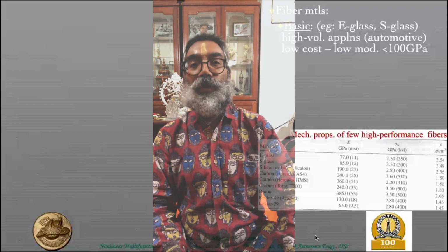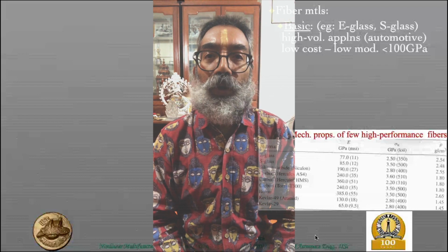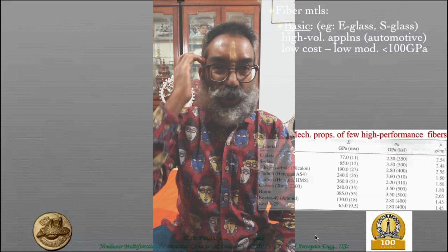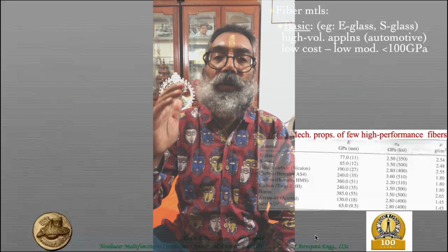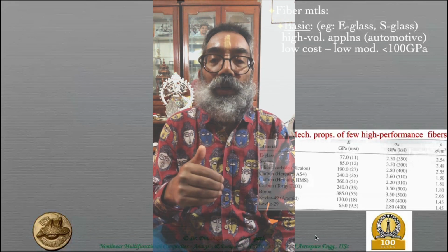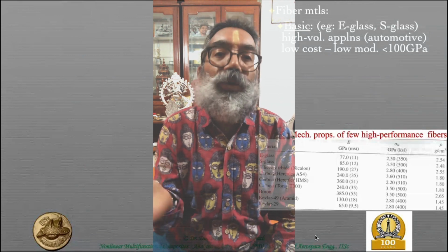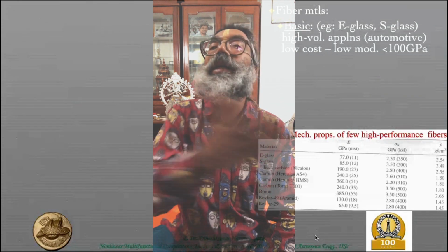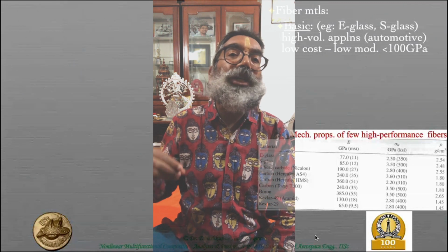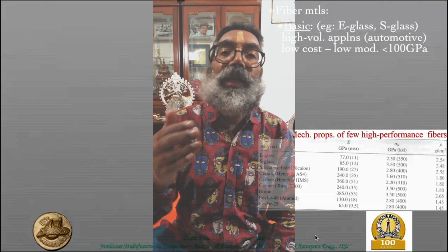That's correct. Very good point you brought about. We will look at all those failure criteria later on, but just to briefly answer your question over here, there are generalized versions of those. It's not that they're completely inapplicable, but you can generalize them to see what the takeaway from them is. But as long as there are things associated with the yield strength, for example, there's no such thing here, so obviously you can't directly take them over here. Any failure or strength criteria associated with a yield strength cannot be directly adapted here. But there are certain ways in which you go about it.